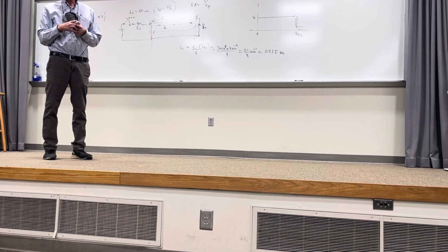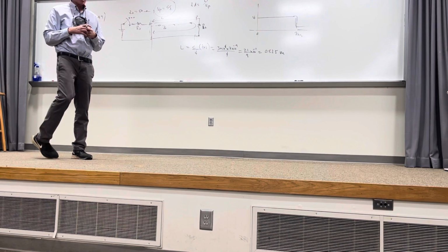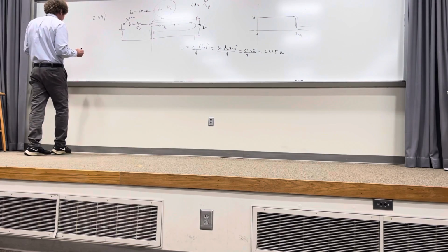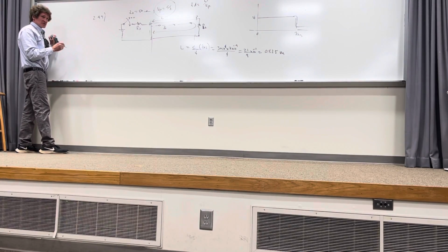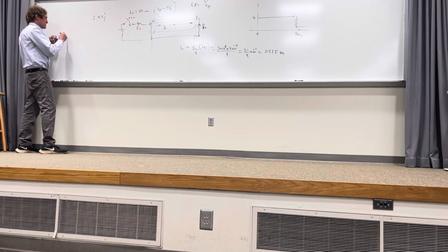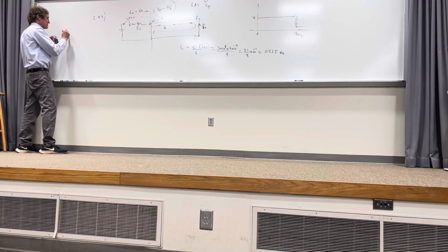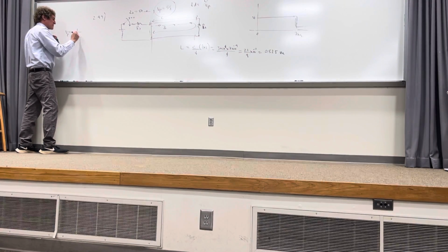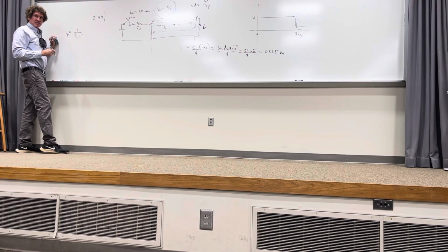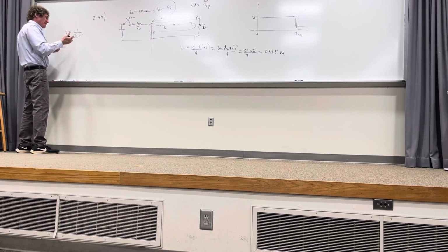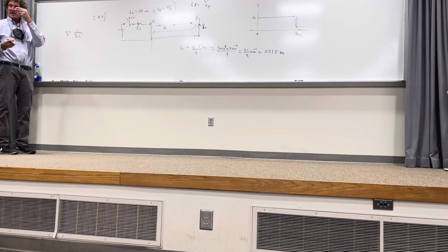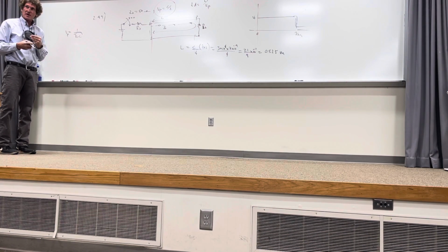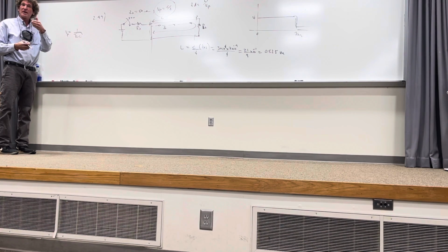Now, this is a little beyond the scope of this chapter's lecture, but we talked about the velocity on the transmission line being the phase velocity, 1 over the square root of LC. You remember that? However, if it's a TEM wave, L and C multiplied together are really the mu of the media times the epsilon. Do you remember that at all?